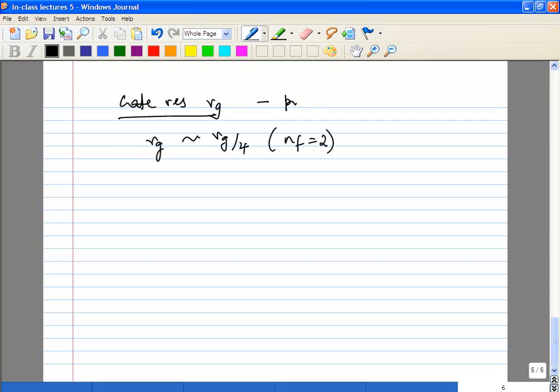And remember, this will be a function of your poly resistance, your polysilicon resistance, and usually this will be given as so many ohms per square. Typically you define it as a sheet resistance. So in general it would be proportional to 1 over the number of fingers. That is normal. It will be some function of it. It will go as if it's inversely proportional to that.